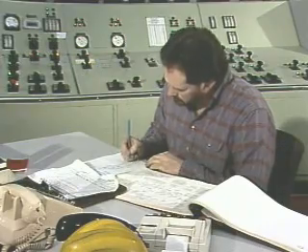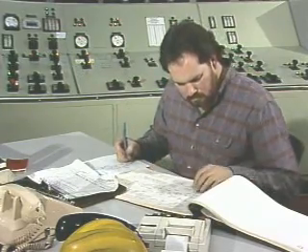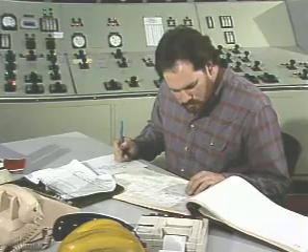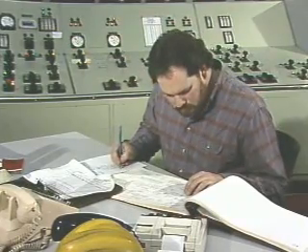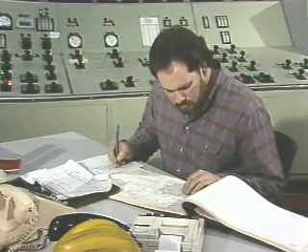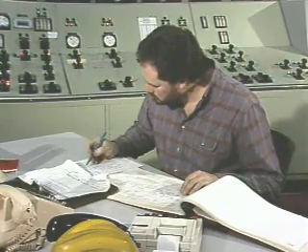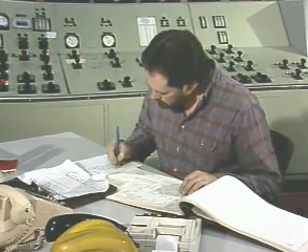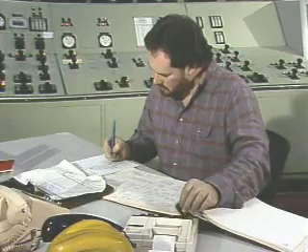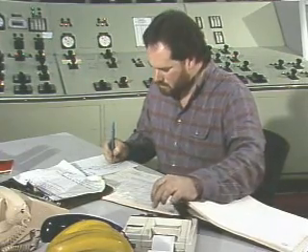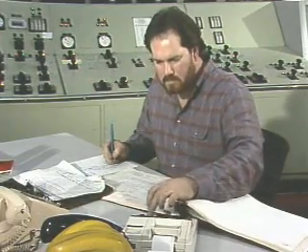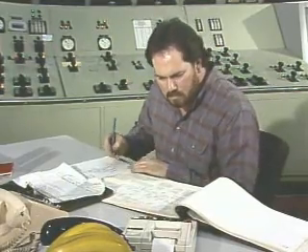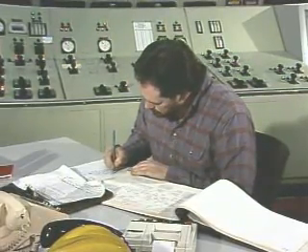To pinpoint the exact heater that's causing the problem, follow a step-by-step troubleshooting procedure, which includes checking the temperature rise across each heater, calculating their TTDs and DCAs, and checking the positions of their normal drain valves. Then compare the actual conditions with the expected normal conditions for the heaters at the given load.